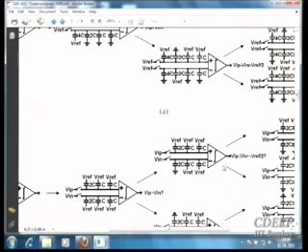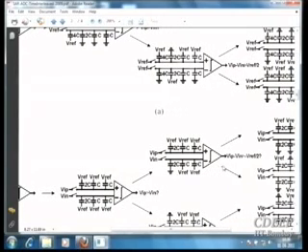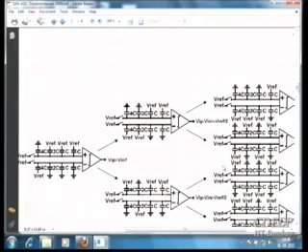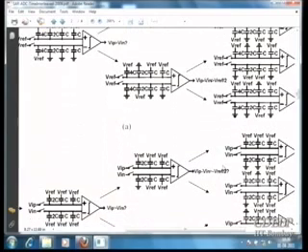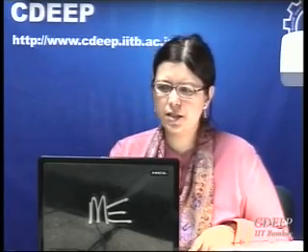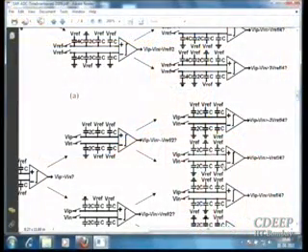Now you go to this decision making: whether VIP minus VIN, meaning VID, is positive. If it is no, you will go here. If you notice, you will have only one transition. They keep one side constant and only one side is connected to ground, whereas here you had both sides switching. This saves power. It also has another benefit: you only have connection to ground, and when you have connection to ground, you can use only an NMOS switch, because an NMOS switch can handle low voltages. You don't have any problem, and with an NMOS switch you will be able to achieve better speed. This is explained in the paper. Therefore you use the switching mechanism which is explained. Actually, it's not required to switch both of them.